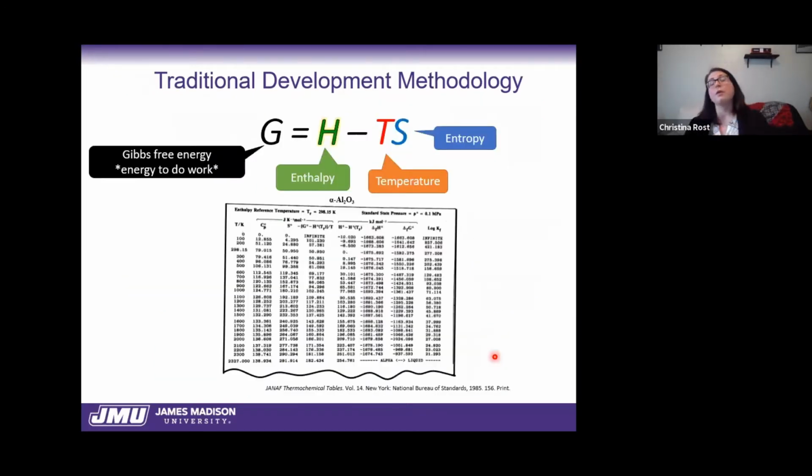Thermodynamically speaking, all of these systems are in equilibrium based on a minimization of their free energy, the Gibbs free energy G, which mathematically is equal to the enthalpy of the system minus the temperature entropy term. Now, in all of the cases of these stable materials, we see that the term that drives the Gibbs free energy to a minimum limit is going to be this enthalpy of formation or enthalpy of mixing. And with some contribution, but not a major contribution from the entropic term.